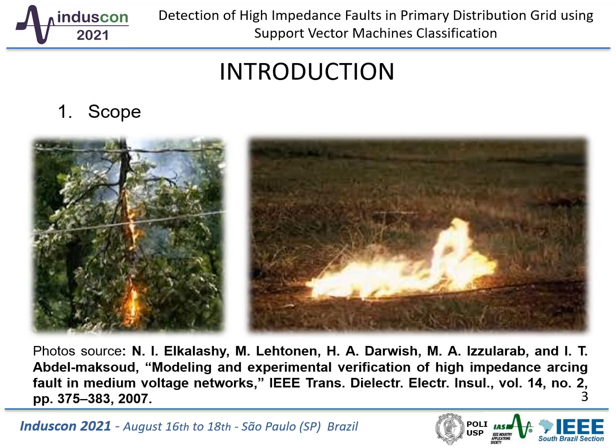One of the most problematic incidents in power distribution systems is the high impedance fault. This event represents a hazard to people, animals, and overall physical infrastructure. As seen in these two photos, a high impedance fault across the distribution grid may be caused by direct contact with trees, for example, photo on the left, or due to overhead conductor rupture, consequently touching the ground, photo on the right.